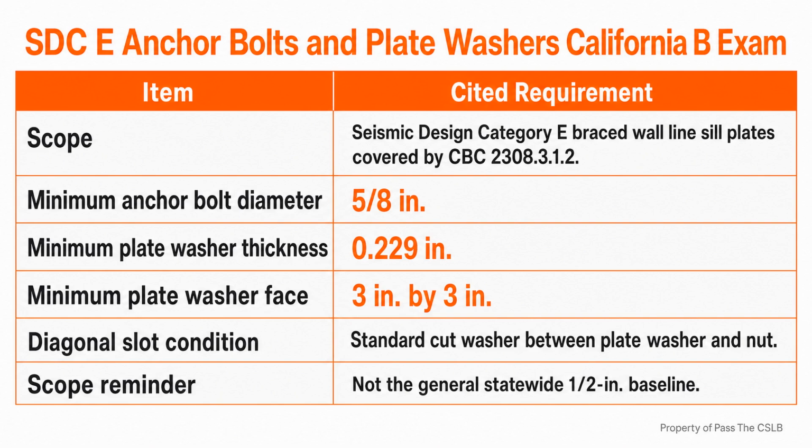That same rule applies to fasteners. A connector with empty required holes, the wrong fastener type, or a modified hole pattern is not fully installed merely because the metal is present. I compare the hardware identification, location, orientation, fastener type, fastener count, and attachment to the approved detail. I also make sure the connection remains visible for the required inspection before covering it. The contractor's value is judgment about when not to improvise.